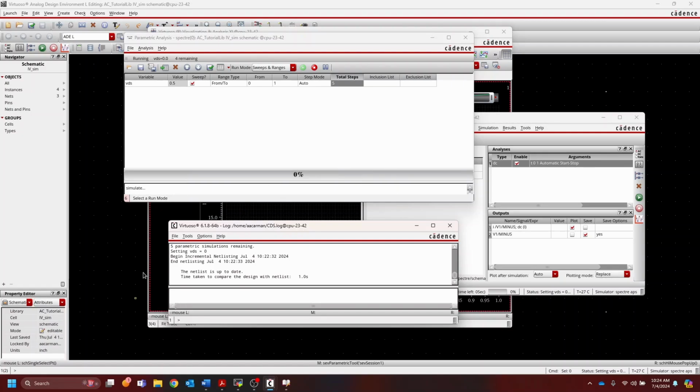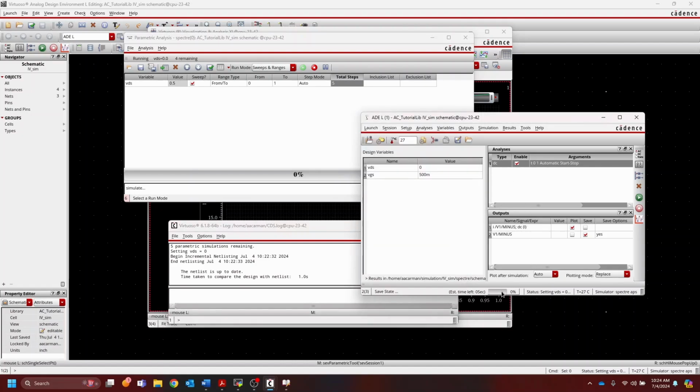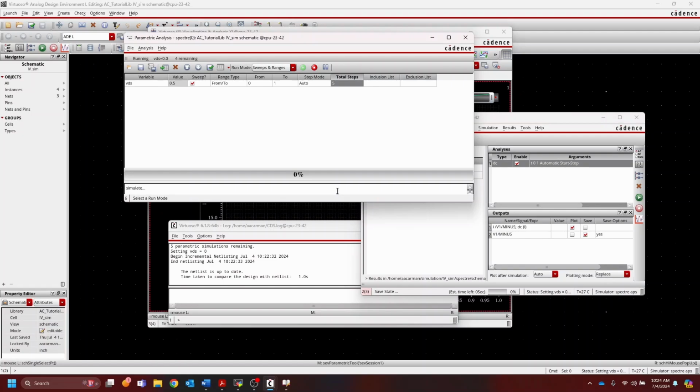As it increases, this is telling us how far along in this parametric analysis we are. Now, you're going to see that this progress bar moves considerably slower than the one at the bottom of our simulation window, because it's having to do that progress bar several different times. Typically, if you're going to try to do something like 101 steps, it's going to take a really, really long time. So it's generally good to do a much coarser step in the parametric analysis window versus a very fine step, since a fine step could take a really long time. So I'm going to step back. We'll do another jump cut, and we'll jump back in whenever this finishes, just to see what the results look like.